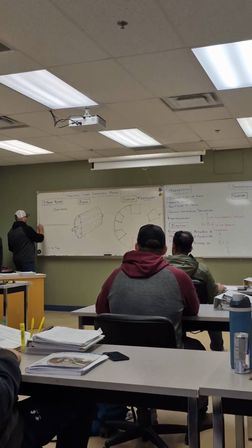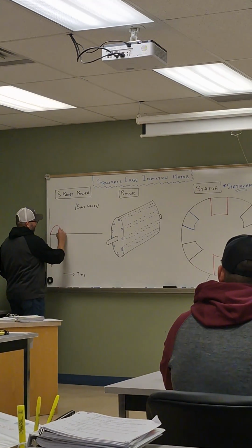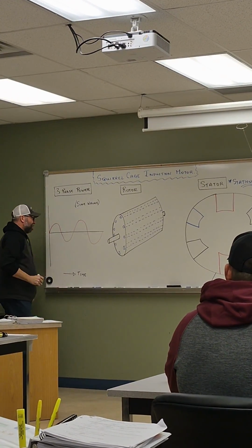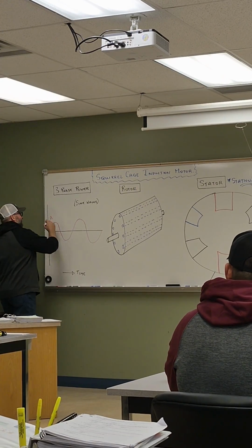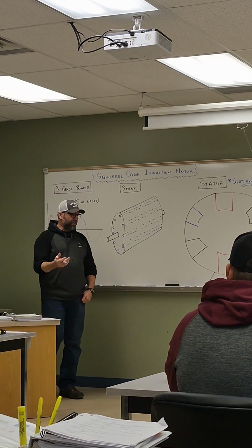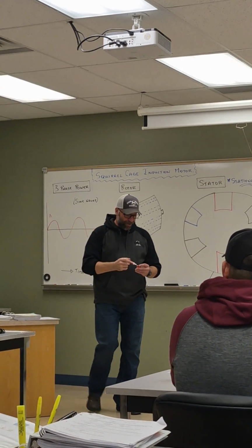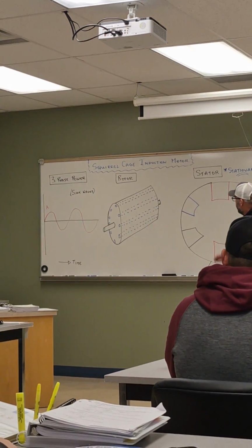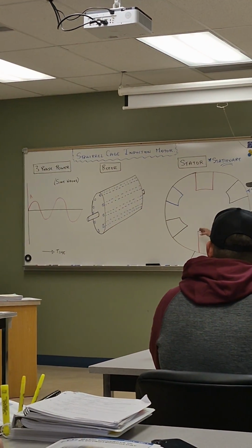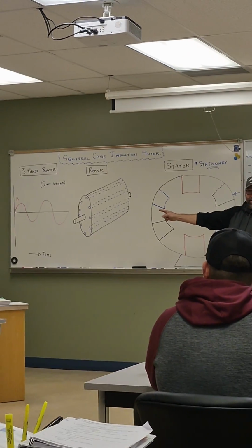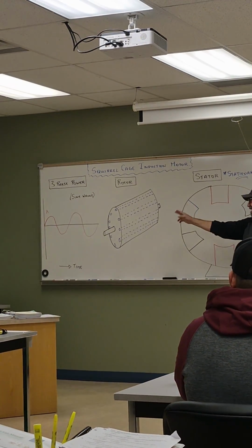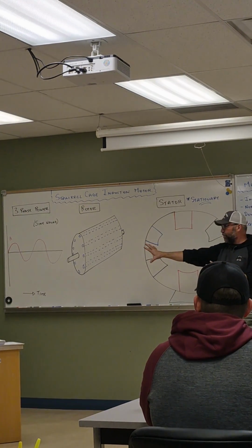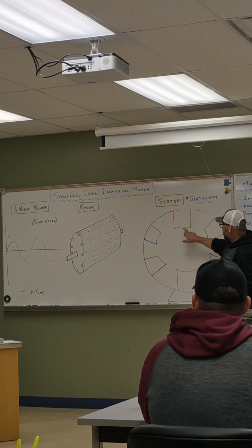I'm going to draw line A first. Here's my sinusoidal waveform, line A. Let's put that it's called line A, or line 1, or red, black, blue in our book. What we do for a motor is very simple. I'm matching color code. You see how these two poles are red and that sine wave right there is red? I take that voltage supply, and we're only going to look at one of the three phases first. I take that voltage supply, and I wrap it around these poles.